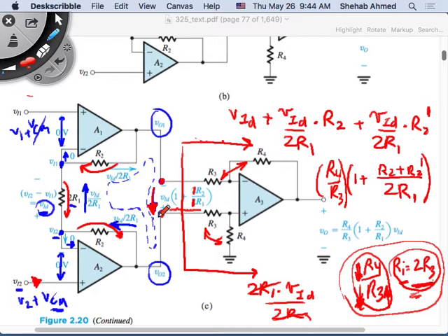It just gave me a gain that is a little higher or a little lower. But it still did not pass the common mode signal through. That's the beauty of this circuit. So now I don't have to have very precise matching between the R2s, and I don't have to have very precise matching between the R3s and R4s, and I get everything I want.